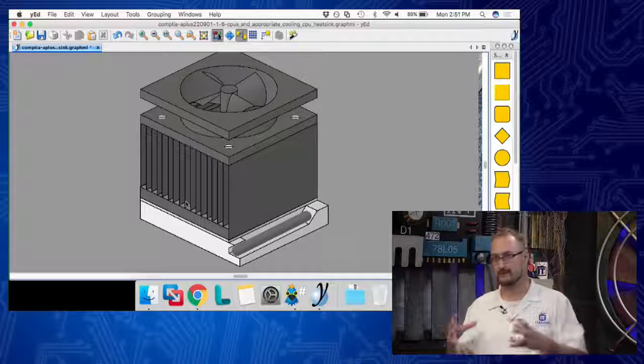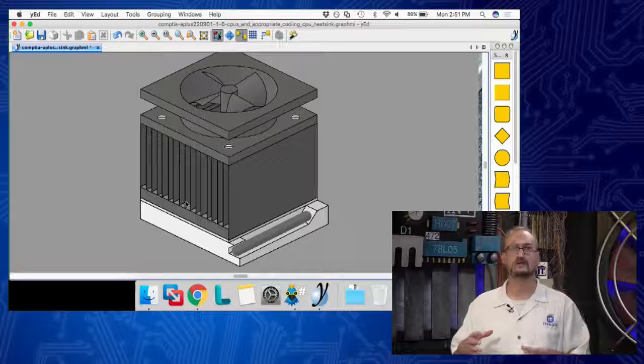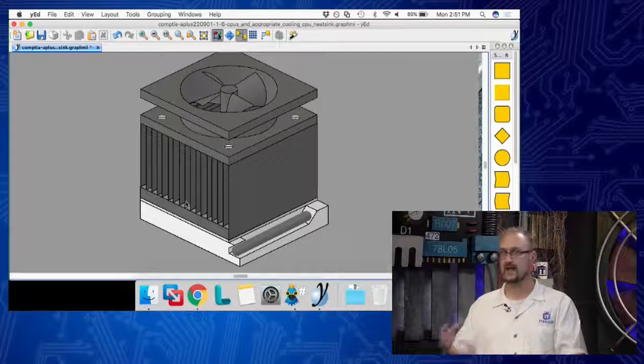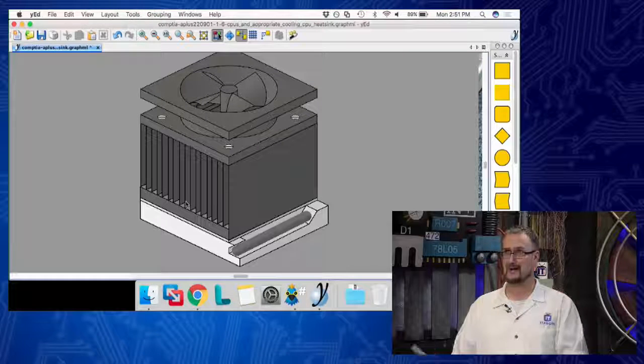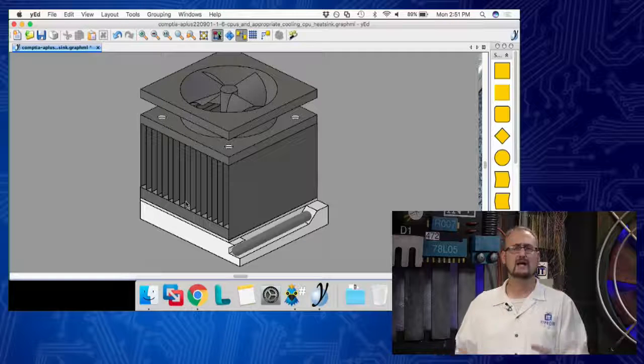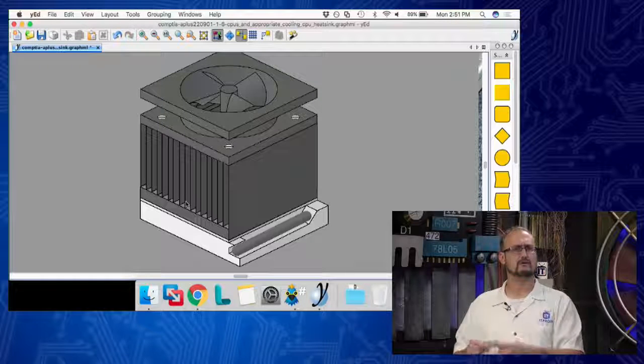You also have what are known as passive cooling systems, and these passive cooling systems are found in things like your very, very small form factor motherboards, like the Micro ATX, Mini ITX, and Pico ITX boards that they have now, and that's because they use very low-powered CPUs, so they don't generate a lot of heat. Right? Low-powered CPU not generating a lot of heat. We can just put the heat sink on by itself, and it's doing its job passively. That's a passive cooling system, or sometimes called fanless, if you will, really for obvious reasons.